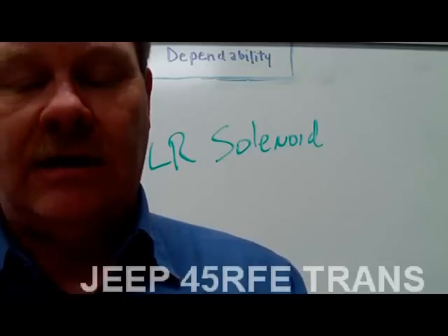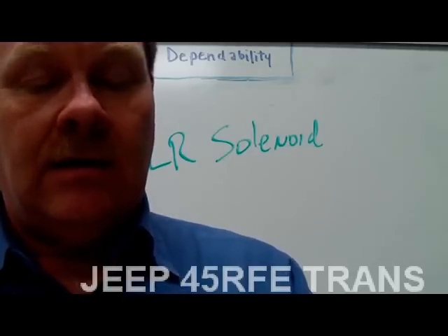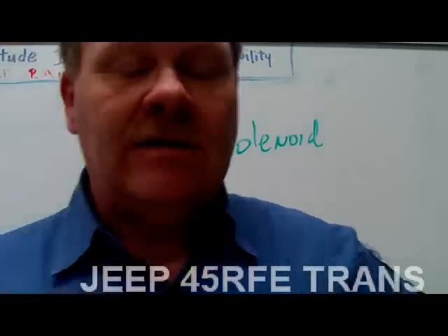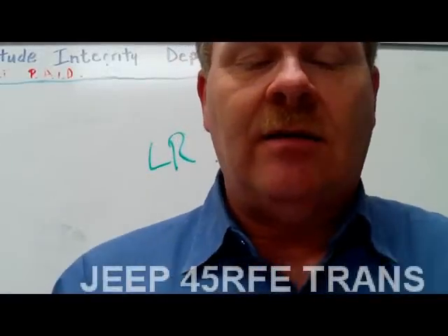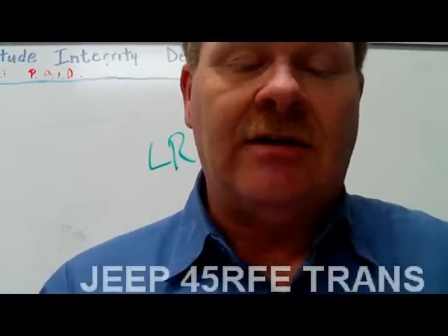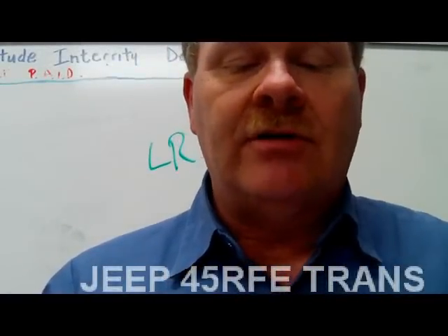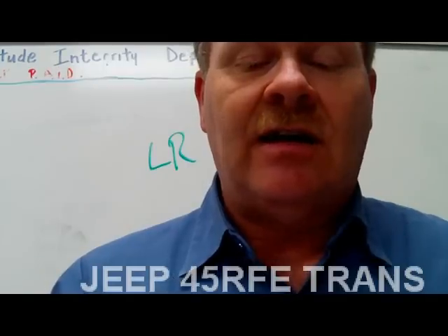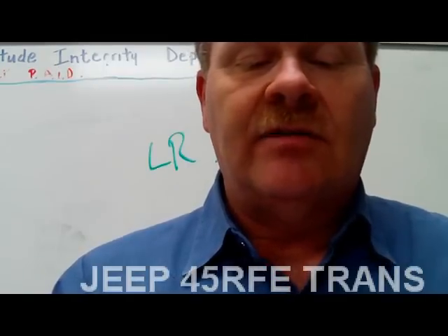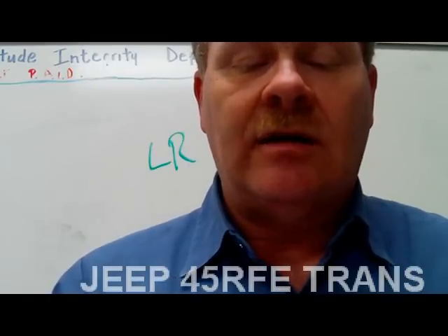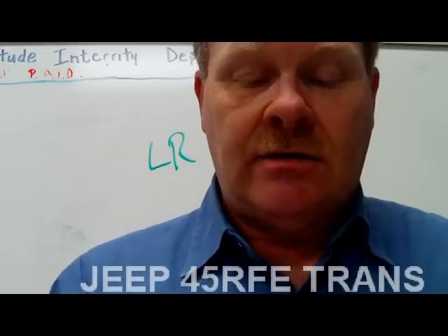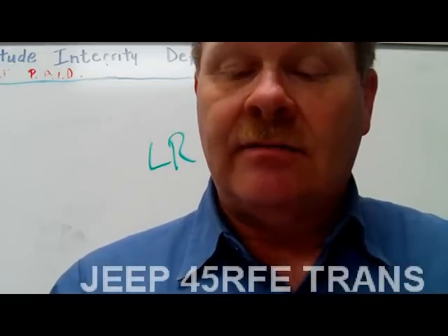They didn't want you rebuilding it at this particular time. Now listen to this. If you do replace the transmission or the TCM, you ought to use the DRB, which is a scan tool, to perform the quick learn procedure, which adjusts the TCM CVI values. Perform the quick learn procedure only after replacing the TCM or the entire transmission. So there's product variability in the field that has to be dealt with.